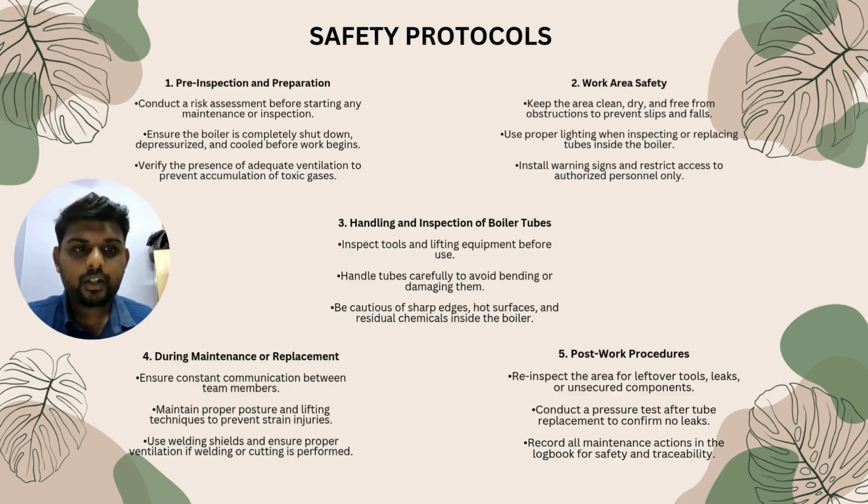Last and final, the post-work procedure. We need to inspect the work area for leftover tools or materials. Secondly, we need to conduct a pressure test to check for leaks. Thirdly, we need to verify all valves and connections are secure before use.